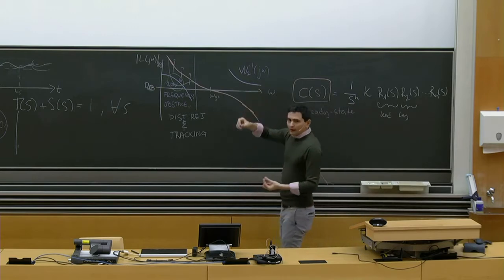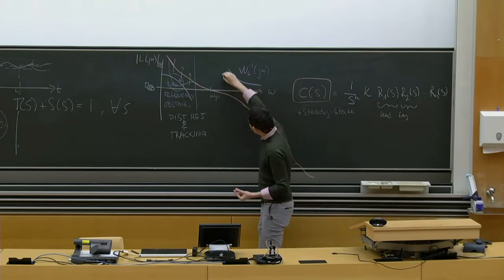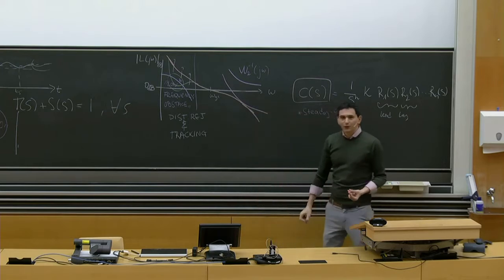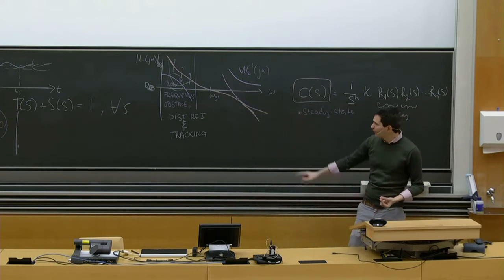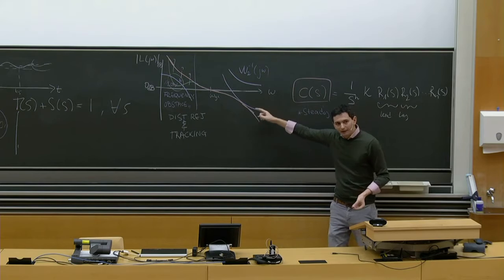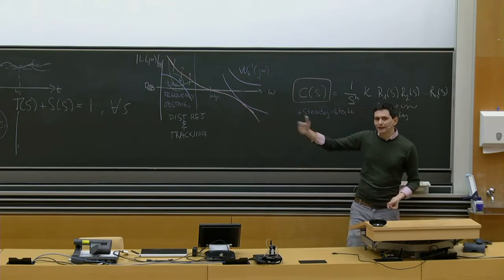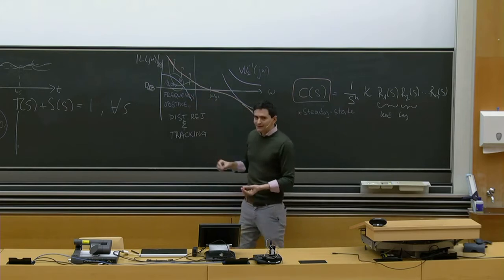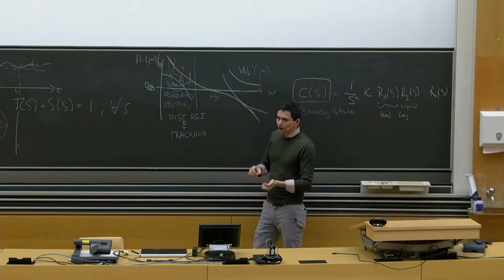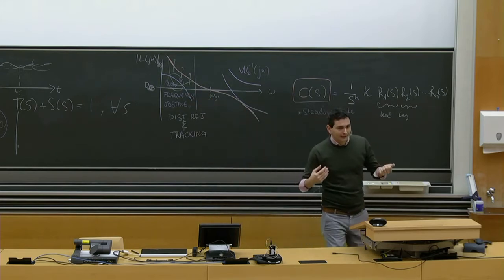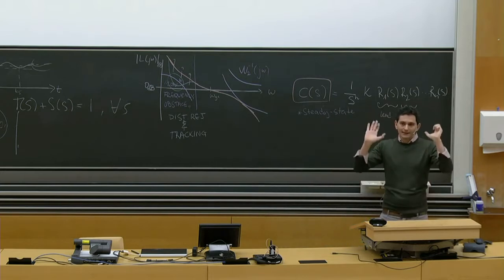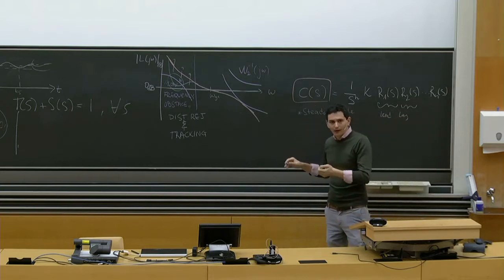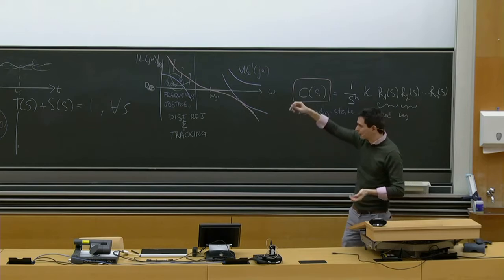Suppose we are doing an exercise where the high frequency obstacle is actually there. So our current design is barely meeting the noise attenuation specifications. So if we want to fix this, well, you could just multiply everything by a higher gain. A positive gain just translates up in the Bode diagram the magnitude of the open loop response, right?